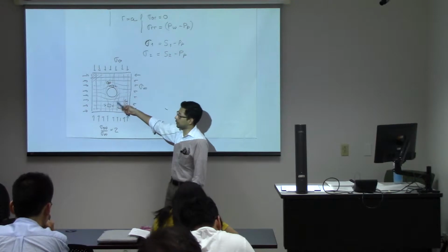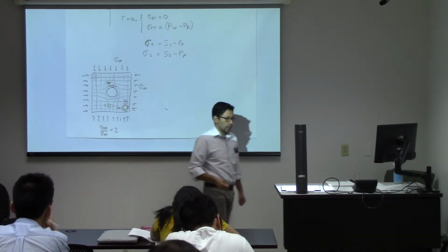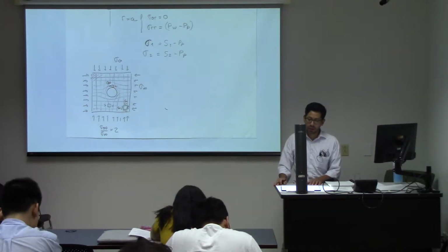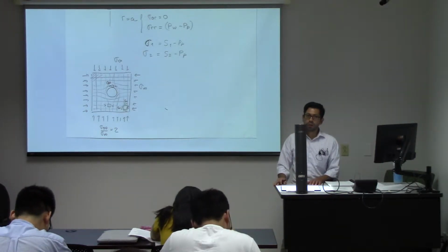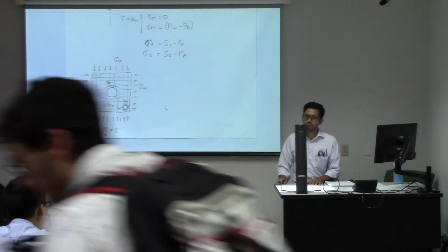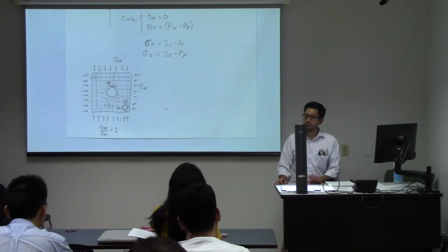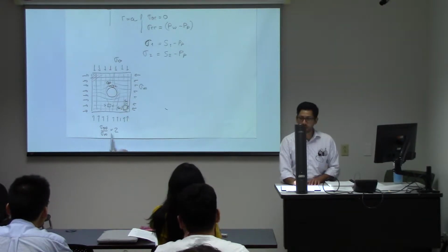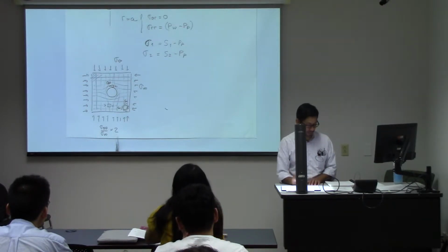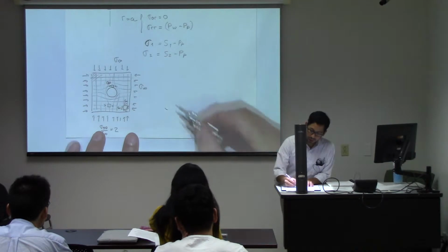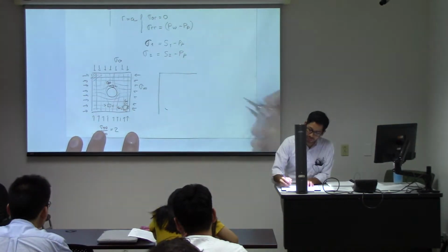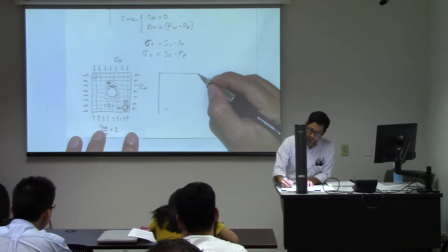If you have a solid that can resist having stress in one direction and no stress in another direction, then you can do that. We'll get later on to failure of rocks, so don't worry about that right now. Important thing over here is this intensity factor. And you will find that if you solve the Kirsch equations, you will see that that's the case.